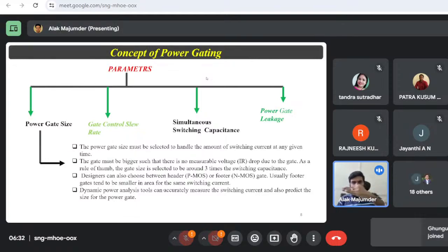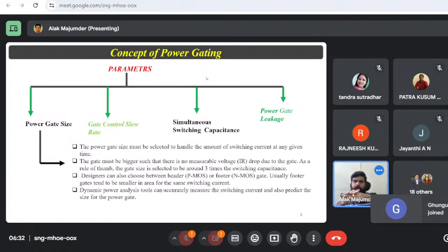You can think of it as an RC circuit. You have a path, which means you have a resistance. You have a gate, which means you have a large capacitance. So you have an RC. If in your communication path you have more RC, you will have more delay. R multiplied by C is nothing but a time constant, right? So it produces the delay over here.